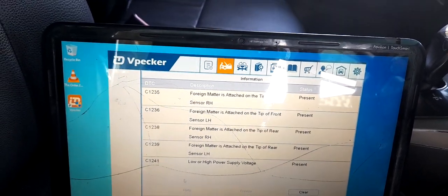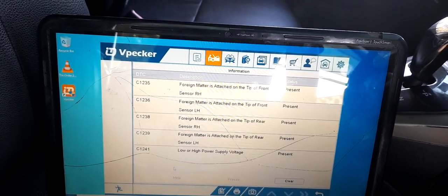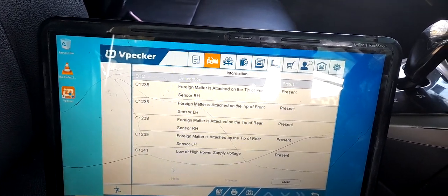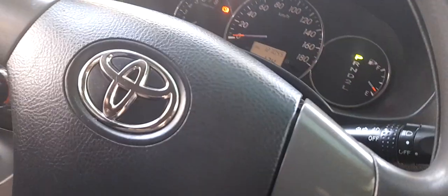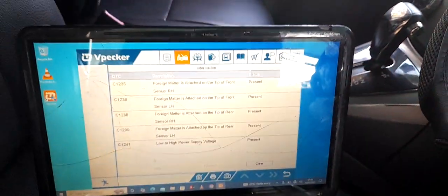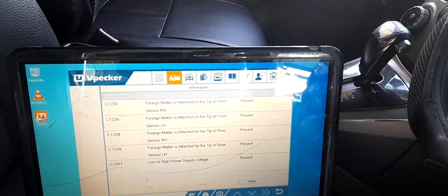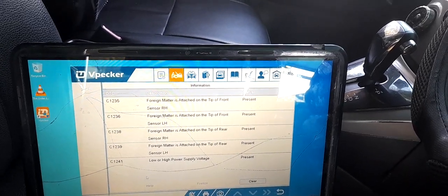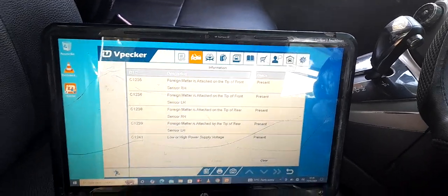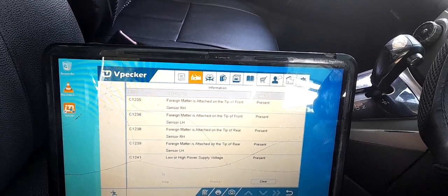Now this means the vehicle was interlocking a brake while in motion, which causes instability. It's like you are on the road, maybe you are doing like 20 or 30 or 40 kilometers per hour, and then suddenly your vehicle swerves, which means the brake was interlocking, maybe in 1 or 2 wheels. So now what does that mean? It means our ABS module has a problem.